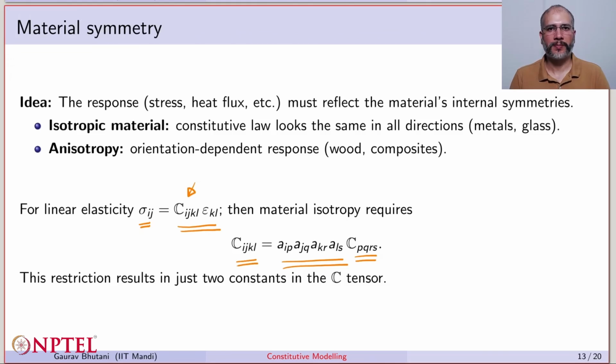isotropic as well. So if you visually look at a fourth order tensor with some components, if you rotate the material axes in such a way so that they point in different directions, even then the C components would still look the same. And this, as again we'll see later, results in the quantity Cijkl boiling down to just two independent constants.